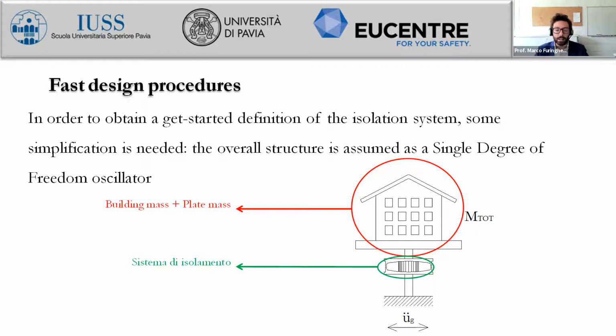The main assumption is focused on what we discussed in the very first lecture of this short course. If you remember, we assumed the building as a single degree of freedom oscillator and the isolation system as a linear elastic spring.